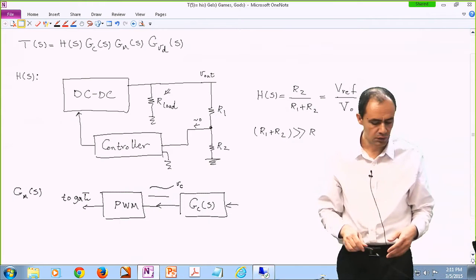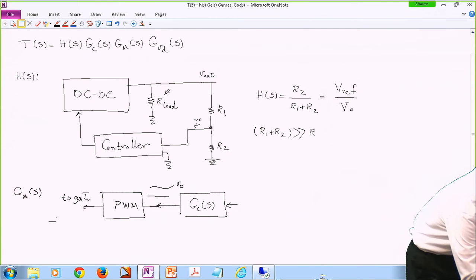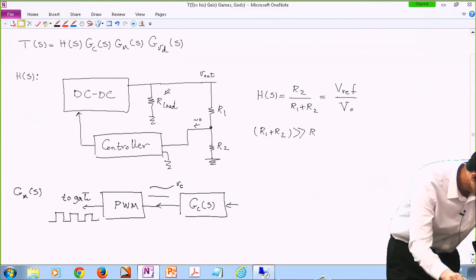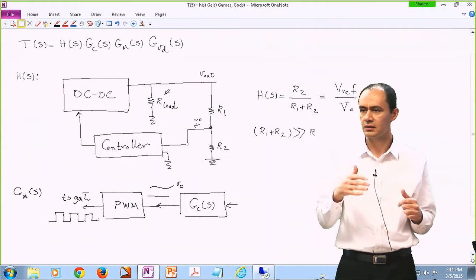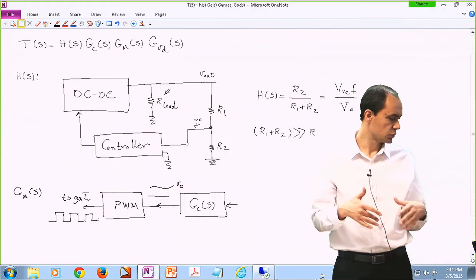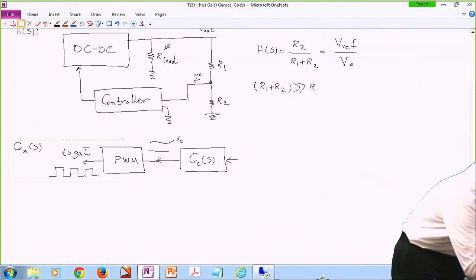Okay. So there are many ways of converting this smooth signal to a pulsating signal. And it's kind of a digital process. So you're looking at a signal that is going up and down continuously to the output that is kind of a little bit discrete, basically. So one method, as we discussed previously, is intersective, which is the most common approach.